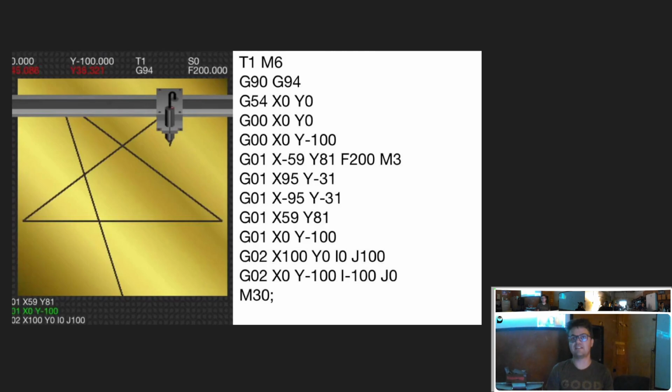It's pretty common for the CNC machines to track the length of the tool inside of the CNC machine itself, and for the machine to compensate for how long the tool is, and for your CAM software to not know the length of the tool. So on the Tormach, our metal CNC machine, when I say T1, that sets the length of tool 1 for the length compensation that it's going to use. M commands are kind of like machine control commands. M6 is execute a tool change. If the machine actually had an automatic tool changer, that would cause an automatic tool change to tool 1 to occur. There, good. G90 is, I believe, I actually am not 100% sure.